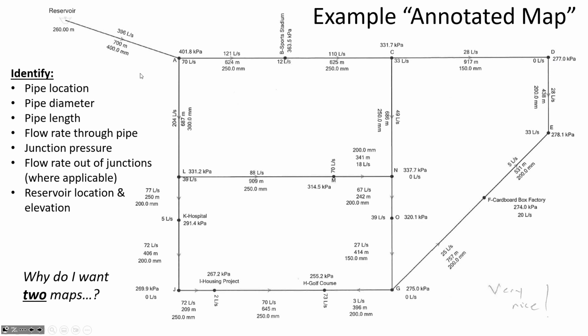And at the condition of zero flow, what I'll be looking for is that none of your junctions have a pressure of more than 850 kilopascals. What determines the pressure at the junctions when there's water going through the pipes is both the reservoir height and also the pipe size. But when it's zero flow, the pipe size doesn't affect the pressure at all. It's only the reservoir height and the elevation of the junction that determines the pressure under static conditions of no flow.